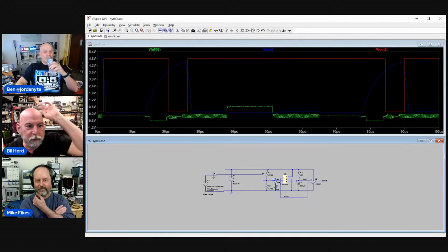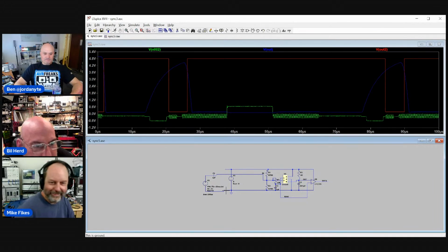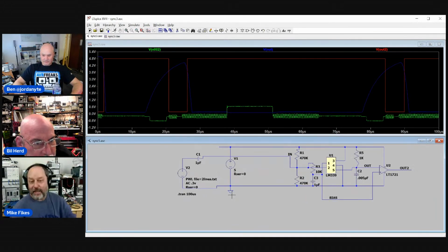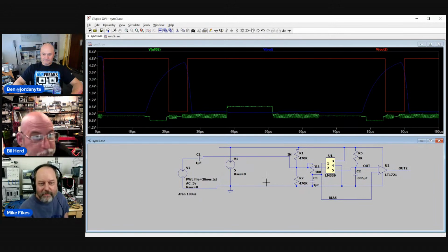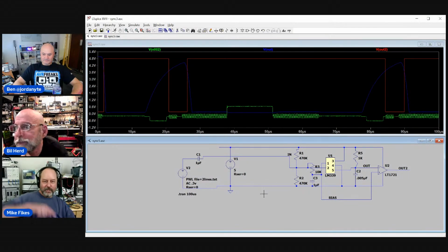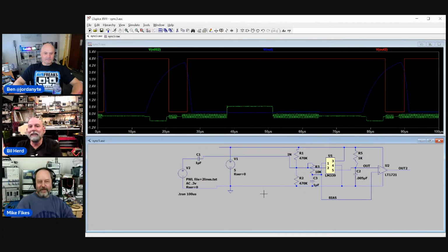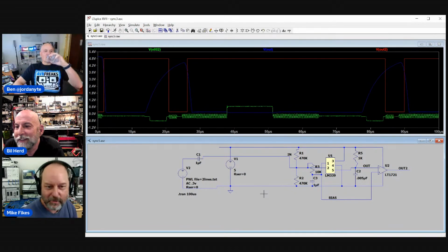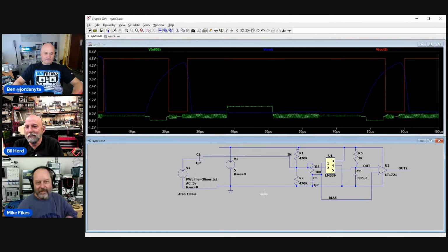I know we're jumping around all over the place, but initially I was using my little signal generator just to make the little blip, right? And you said, hey Mike, can you make a little circuit that would find that blip? My reaction was to amplify it and then throw it into a 555 to pulse extend it. We simulated it and it worked.